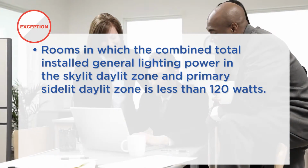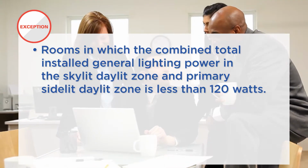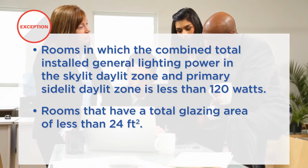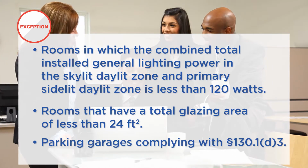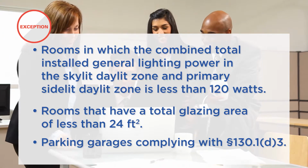Rooms in which the combined total installed general lighting power in the skylit daylit zone and primary sidelit daylit zone is less than 120 watts, rooms that have a total glazing area of less than 24 square feet, and parking garages complying with Section 130.1d3, which we are going to go over next.